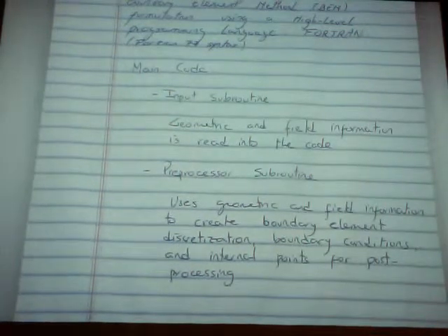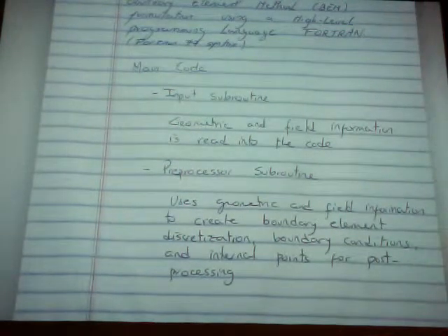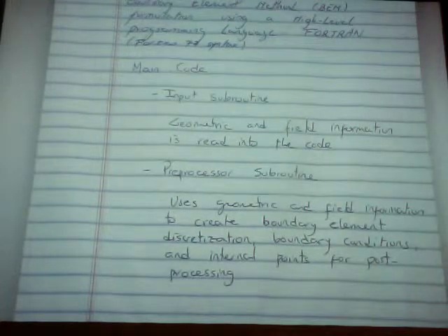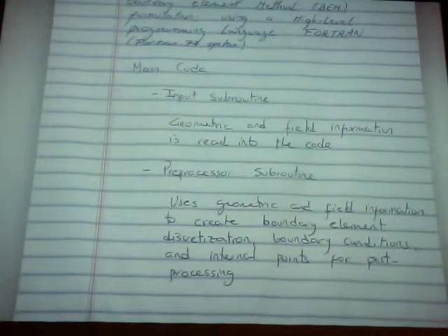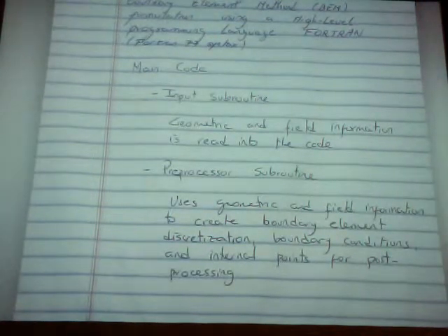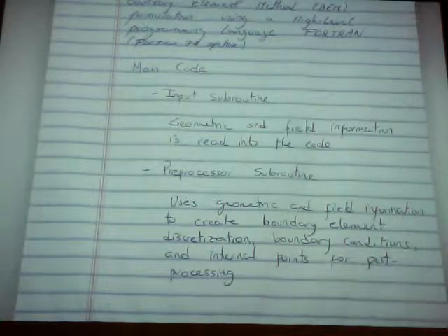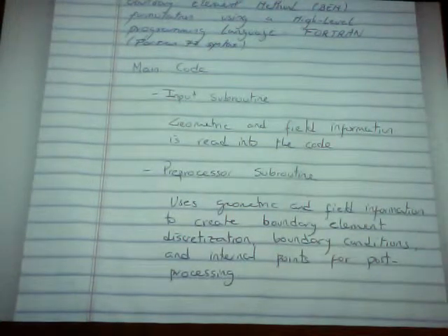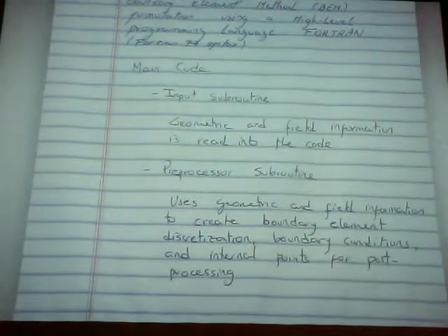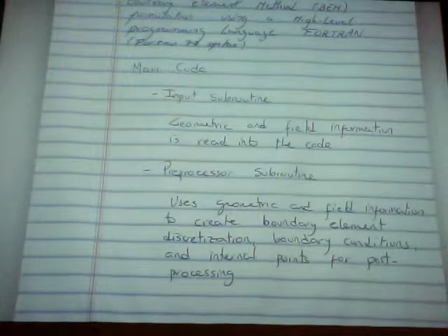It means getting temperatures and fluxes on the boundary. Okay? If you want to display where your temperature contours are or what your flux vectors are, you cannot do it with just that information, right? You need information inside. So the information inside is going to help you construct a heat map, and it's probably going to help us construct a vector plot. All right? So we need internal points just for post-processing so that we can output the results.